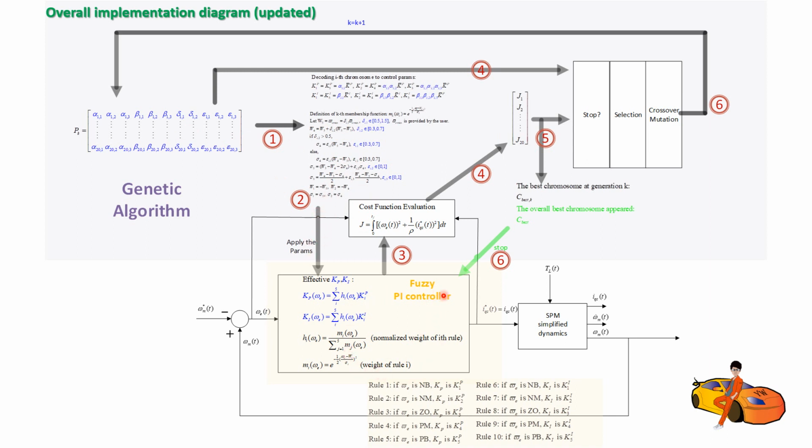And this fuzzy controller, instead of outputting IQS directly, has an effective Kp and Ki, which finally gives me IQS, but I want them to be represented explicitly, such that I can explain to other control engineers or audience exactly what Kp and Ki are commanded.